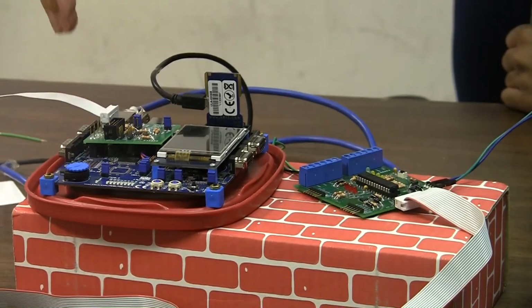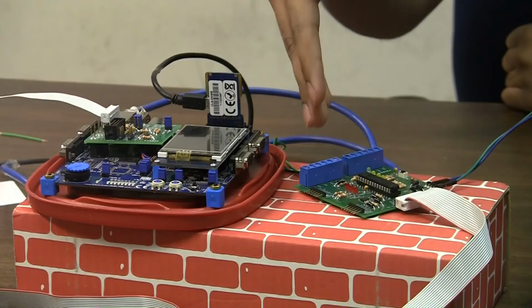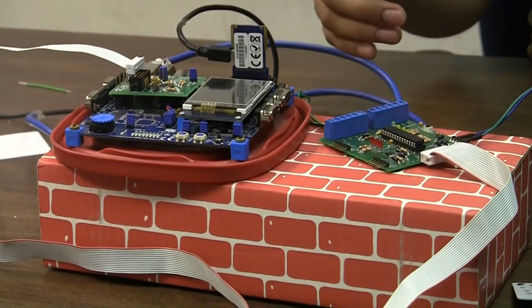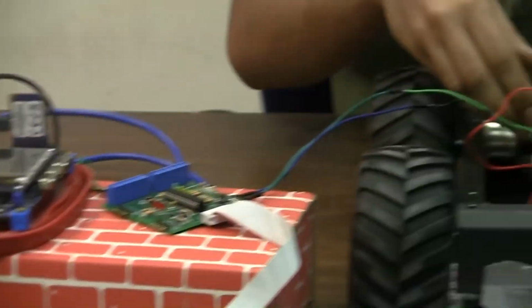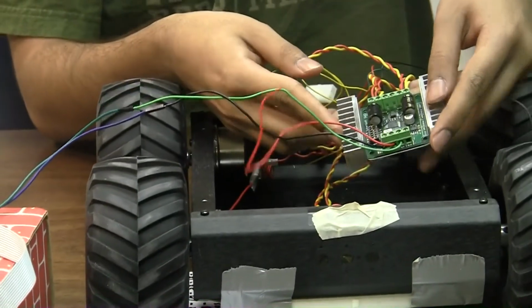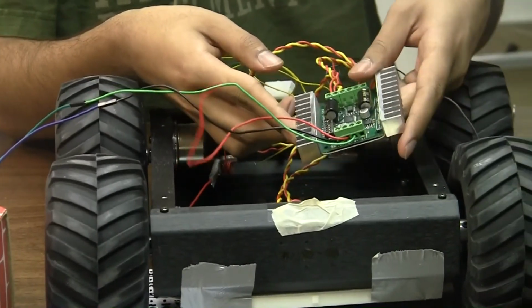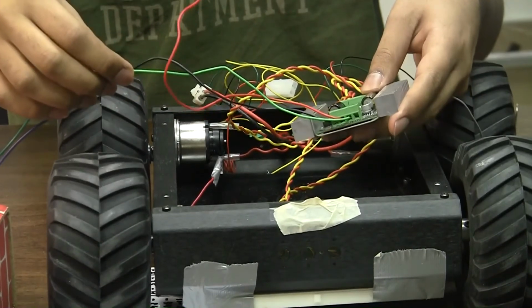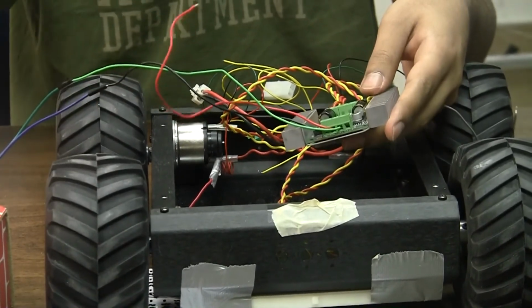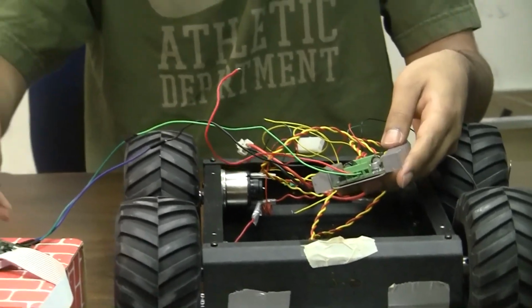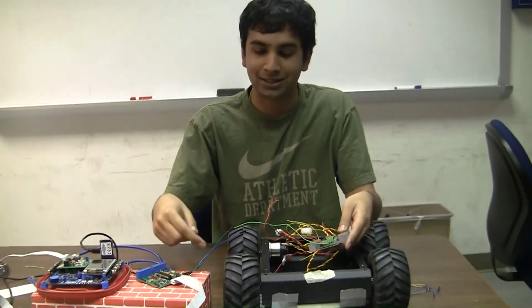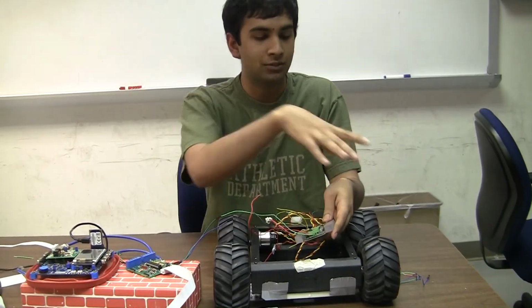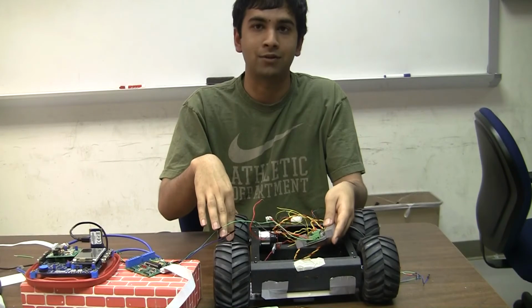The ARM will send motor commands via I2C to the motor PIC, and the motor PIC will translate whatever message it receives into a UART message, which it will send to a Sabertooth motor control. This Sabertooth motor control has a power, a ground, and an RX pin, which basically means the read pin for the UART. When the motor PIC sends a message to the Sabertooth, it translates it here and sends it to each side of the rover.